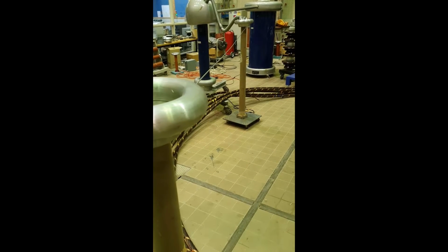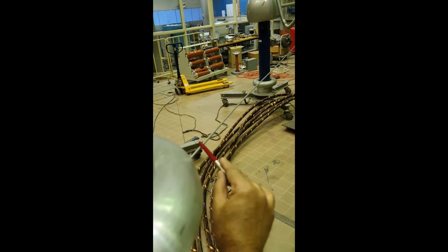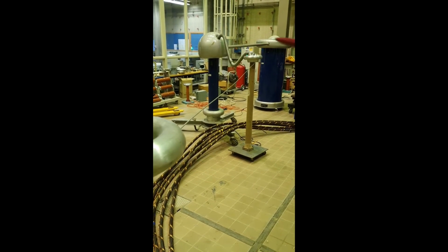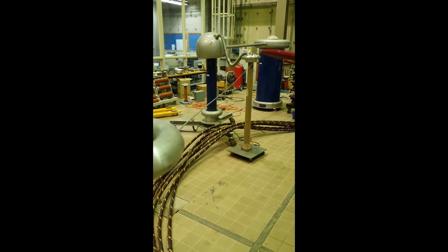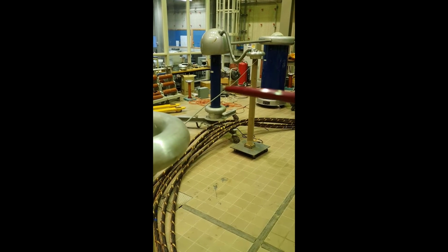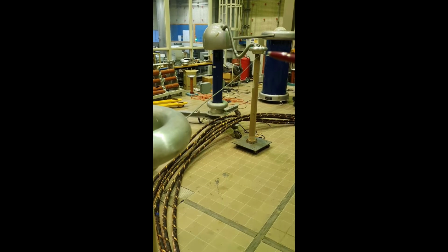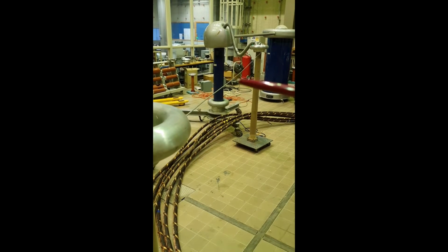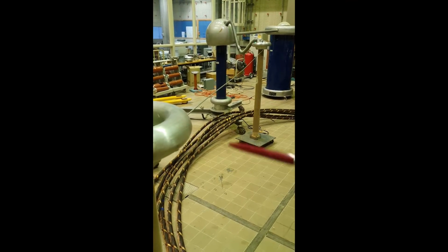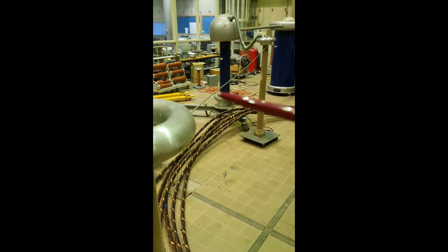You can see this is the transmission line here. This transmission line will be at high voltage, so it is connected to the HV source there, which you can see, this HV source, this AC transformer. So it's a divider, and this is one end of the transmission line, and this is the second end of the transmission line. This transmission line now is smooth without any rough surfaces, and we need to measure the height of this transmission line. So this is 1.5 meter above the ground, so this will be needed for your calculation, and the diameter of this wire is 4.5 millimeter.